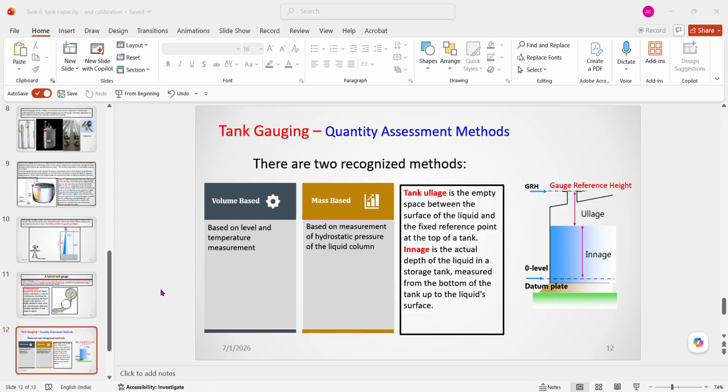When it is not touching, it is due to its own weight, which gives some tension to the wire. When it touches the liquid, the buoyancy force acts on it, and then the tension will decrease. The weight will decrease. The sensor detects this weight change and commands the motor to adjust the displacer position, maintaining an exact balance.